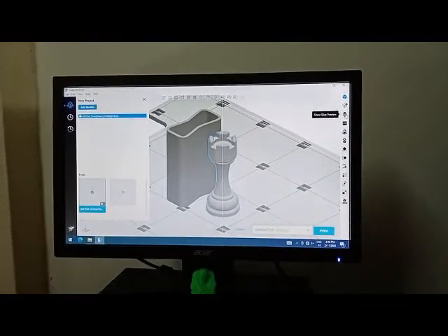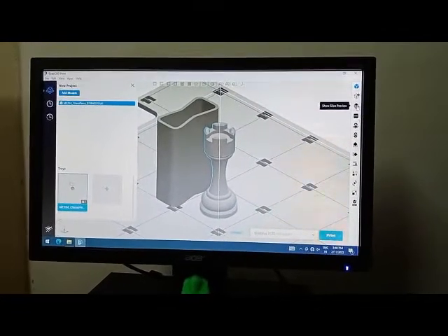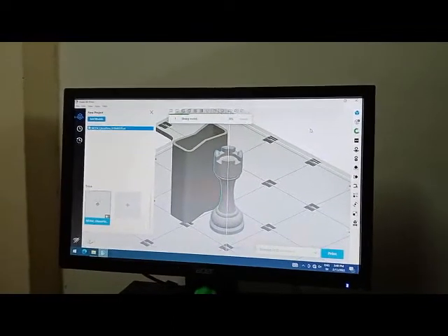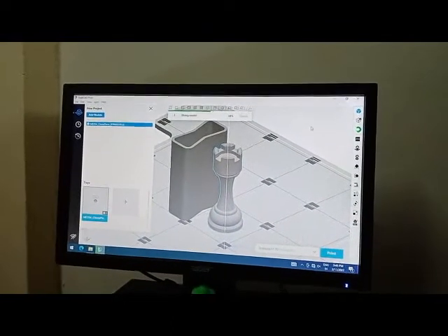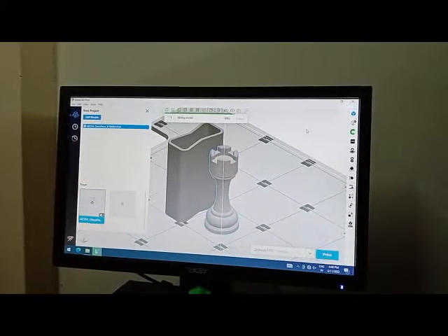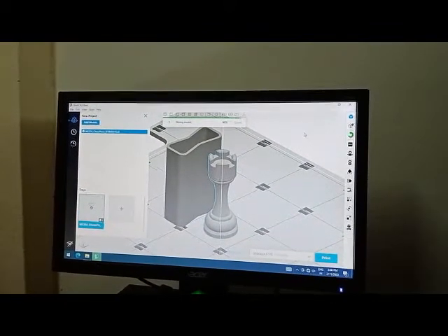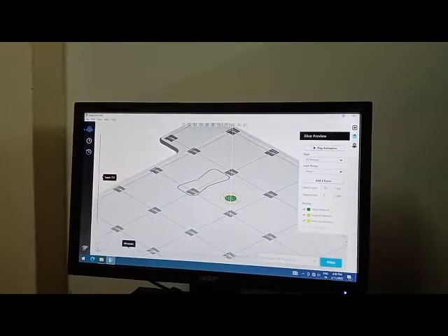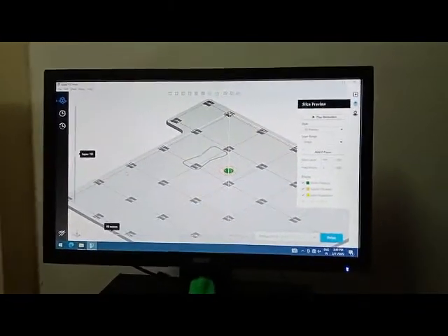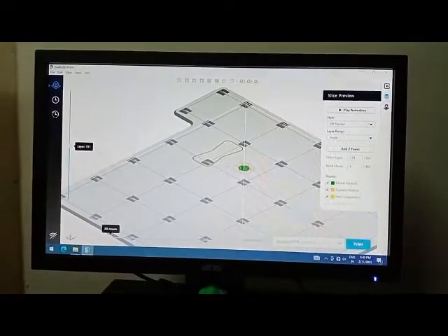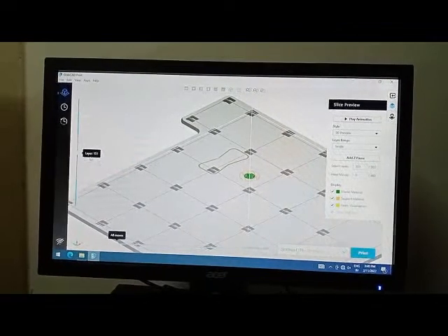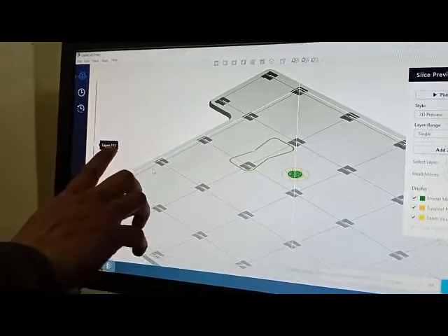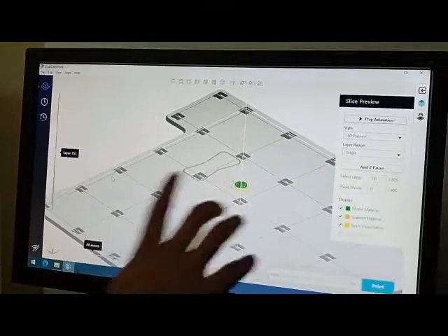This is the option where we can see the slice preview. Slice preview is something where we can view the number of slices or number of parts the machine will print, in a layer-wise manner, fine. I'll just show you the meaning of slicing, what we can view in the slicing part. See, this is the part we have here, fine. In real-time condition, this is how the part will look in the 151st layer. In the 151st layer we can view this type of thing, fine.